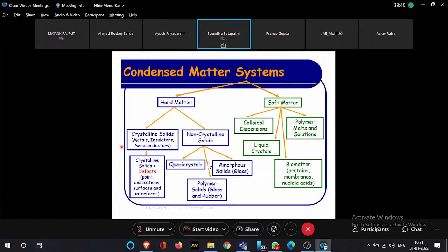In the case of the insulator, the difference between the valence band and conduction band is high, something like 6 electron volt. You know what the definition of an electron volt is, right? It is the amount of work you need to do if you want to pull an electron against a 1 voltage difference. The amount of work you have to do is called 1 electron volt. So it's a form of energy. If the energy difference between the valence band and conduction band is 6 electron volt or more, then it is very, very difficult